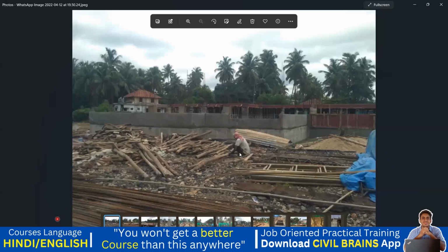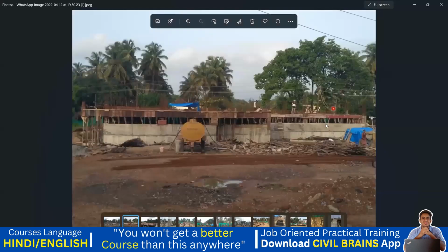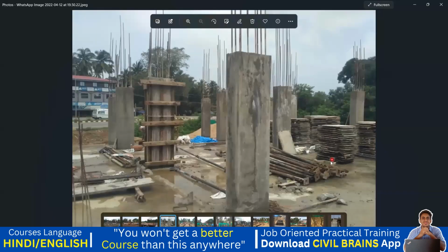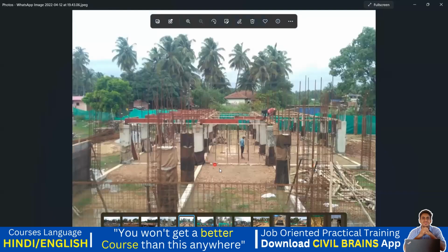Practical site images for the same building which we had executed. So this is my retaining wall. Once the retaining wall is constructed, you can see these are my columns, and this slab centering, you can see, is my basement slab. Okay, I'll take you to the next. You see here, the retaining wall was done, and here they have put up the slab centering for the basement slab. All these are your basement slab centering, and the beam reinforcement whatever we had seen, 16 diameter, 5 bar at the top, 16 diameter, 3 bar in the bottom, everything they have arranged practically on the side. And yeah, now you can get a better idea.